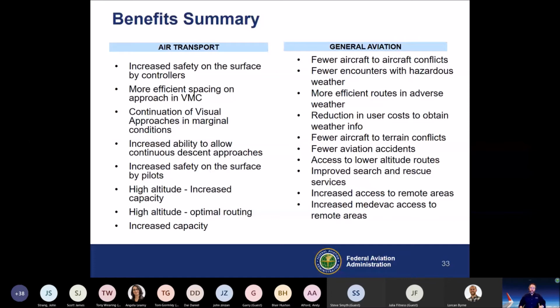Kind of an interesting perspective, because you can imagine if you're only seeing in the long-range environment a radar update every 12.5 seconds, that's a lot of time to elapse where you're trying to figure out where that target's going to show up again in the future. With ADS-B, you're getting it every second, and it really enhances the controller's ability to make good decisions in the moment.